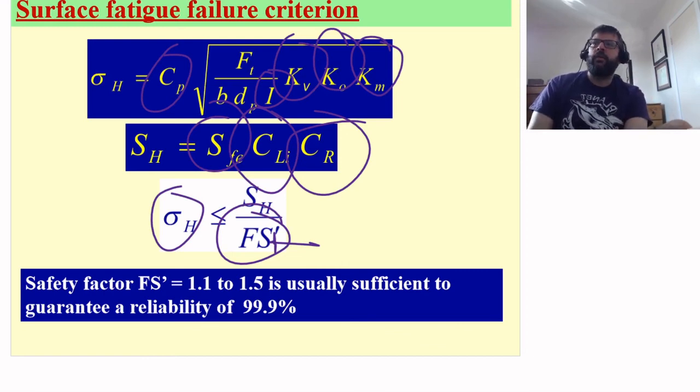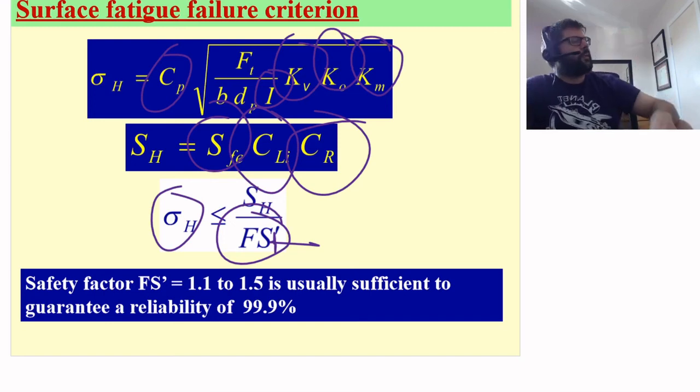Which is why you do tend to get case hardening, because case hardening allows you to essentially apply heat treatment that targets the weak spot. It targets our surface fatigue. It increases the hardness of the surface, while not really touching the strength in the core, where we base our calculations for the bending fatigue.